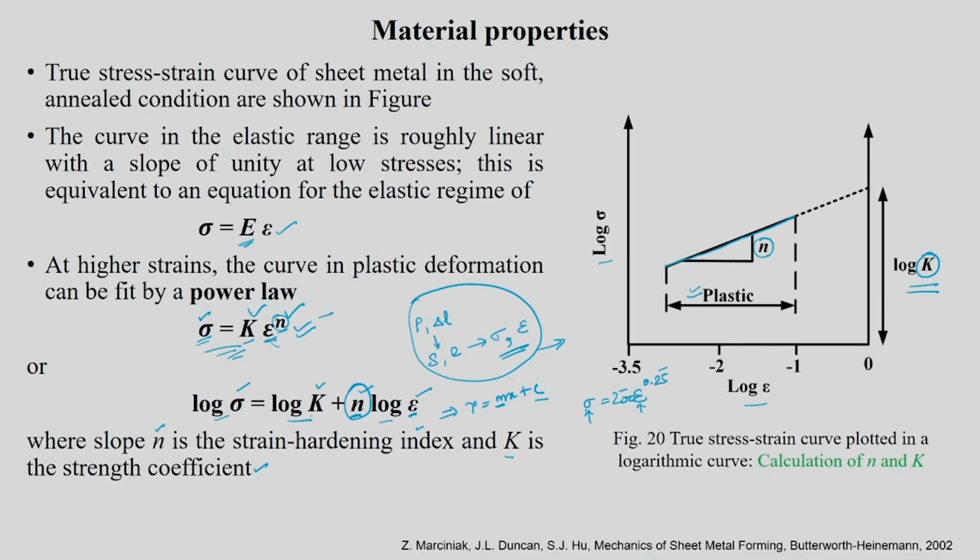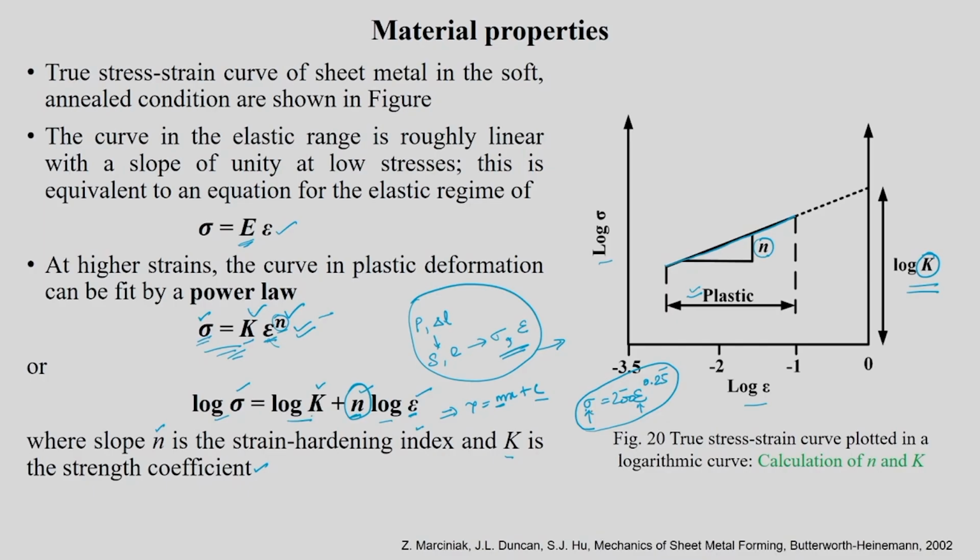Okay. So, now you will see that from a tensile test you are going to evaluate this type of equations, but in the tensile test the material is going to fail at one particular strain, while actual sheet forming operations may undergo large deformation where strains can be much larger than the strain that you see in the tensile test. So, in that region of deformation where you do not have data, you can extrapolate this equation and use it to relate sigma and epsilon beyond the tensile test also.